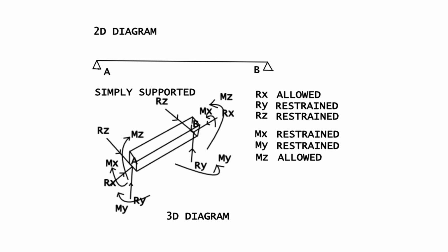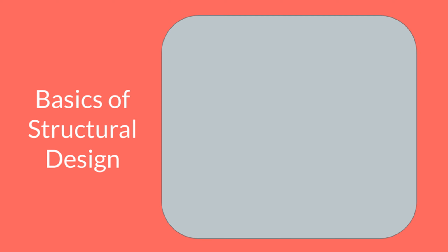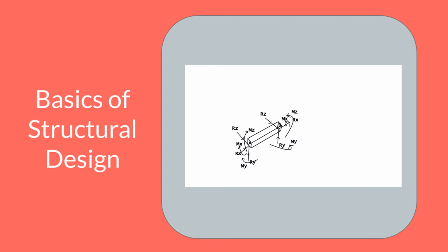Joints. It is important to understand the types of joints and their provision at a selected joint. That is like column to beam, beam to beam, and slab to beam, etc. At each support, there are 6 degrees of freedom: 3 for translational displacement and 3 for rotational displacement. To understand the concept of degrees of freedom, let us consider a bar with a flag. To hold it in position, all the 3 translational displacements and 3 rotational displacements shall be 0. All shall be restrained.